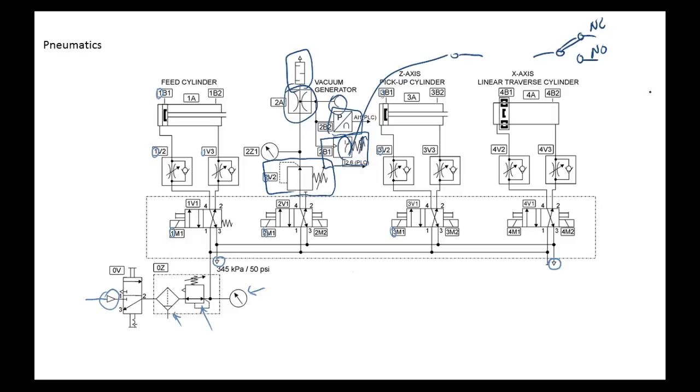When we look at our sensors, none of ours have that. But the color code for sensors is set up for 4 wires, and the only difference is if you have a single pole double throw switch in there. Most sensors are either going to be normally closed or normally open, but you can buy them with both on it. So good question. Any more?